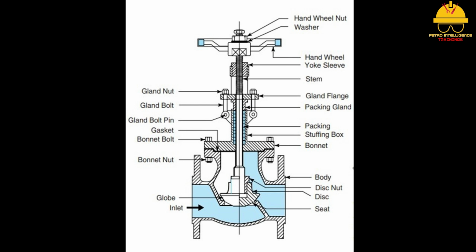The stuffing box is typically located where the stem goes through the bonnet. The stuffing box is a recessed area specially designed to allow packing to be mounted around the stem. The packing gland is a device used to compress and secure the packing material into the stuffing box. The packing gland nuts are designed to be evenly tightened by an operator to stop leaks. The handwheel is attached to the valve stem. The handwheel transfers rotational energy to the stem. This rotational energy controls the movement of the flow control element.